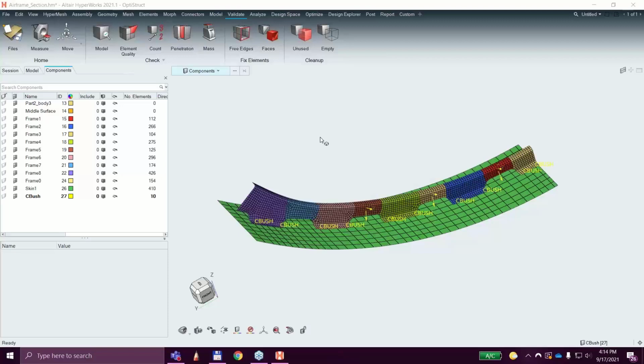One of the strengths behind HyperMesh is the fact that it is a universal preprocessor. It's really blind to whatever software you're going to be running your analysis on. We can equally easily set up an analysis for any of the popular commercial solvers out there. What we're going to be talking about is a setup for our OptiStruct solver, but the processes I go through are going to be very similar, with maybe some minor deviations, for any solver that you want to set up. Now, I will run through the entire process of bringing a model in, cleaning it up, meshing it, establishing the materials and the properties, setting up the loading conditions, and we'll run it and then take a look at the results in HyperView.